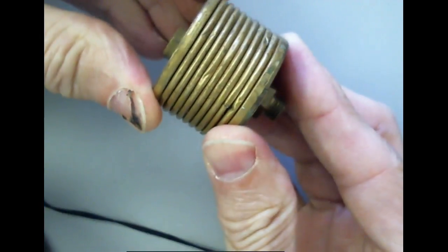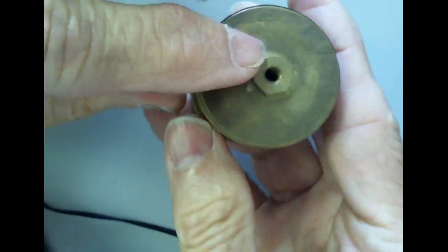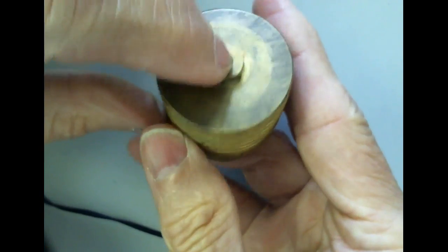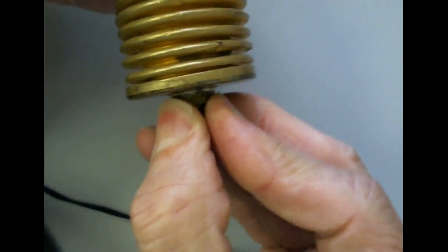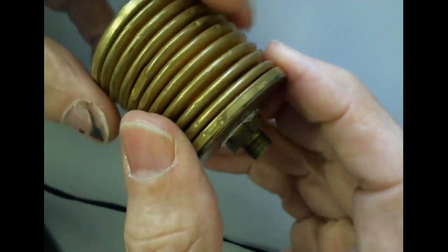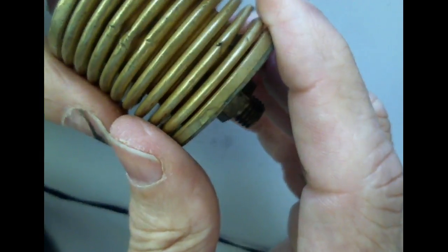It's going to contract. And then of course this mounts permanently on one side to a surface that doesn't move. So when the bellows moves in and out, we can use that to indicate pressure. What actually measures pressure? Well, that's what we're talking about. Normally these sensors have to be combined with another element to get a voltage or current or whatever output.